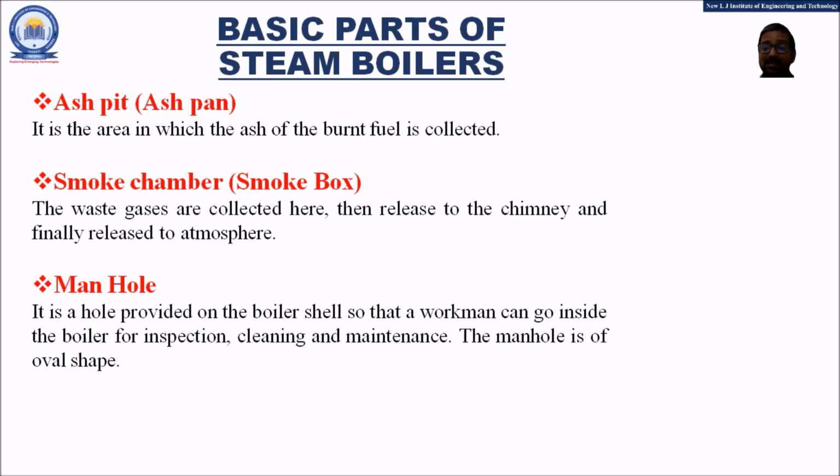So it is very essential to provide this opening so that the workman himself can enter the boiler for inspecting the different components, for cleaning as well as for maintenance. Considering the mechanical design, the manhole is of oval shape.